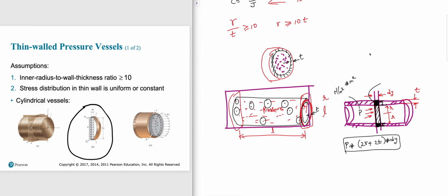Right. But by the way, if you observe carefully, I have to remove this 2t here, because the pressure inside the tank is only here wherever the gas is in contact. So the gas is not in contact here, neither is the gas in contact here. So sorry, I have to remove the 2t. So this highlighted solid black with this red color border, that is the material that is opposing P times 2R times dy.